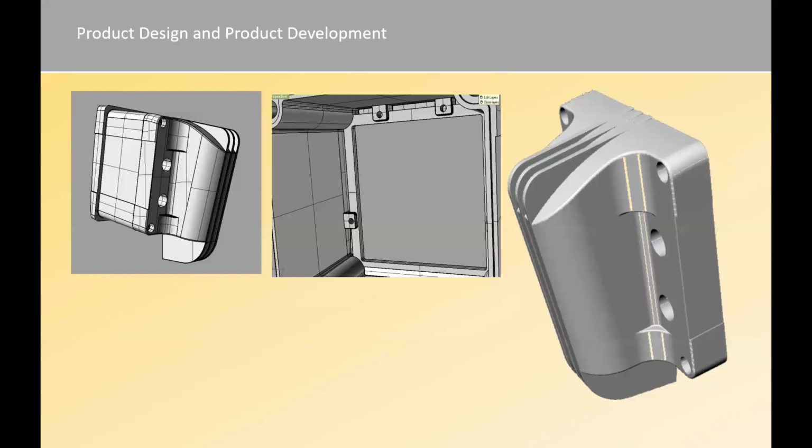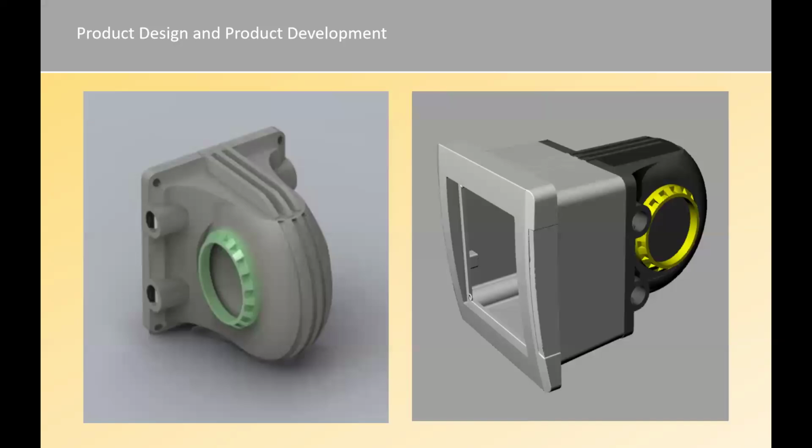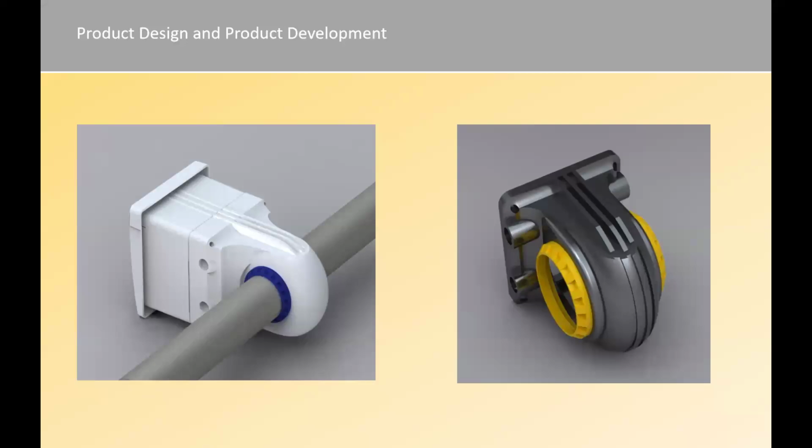So with this product, we developed 6 products with different variants. This was one of the final designs, and then we developed 6 products out of it. So once we change the back cover, if there is no battery involved, then we have this kind of setup where the product is mounted on the pipe itself. And there was a variable ring given to this pipe. So pipes of 25 mm to 60 mm outer diameter can be mounted.